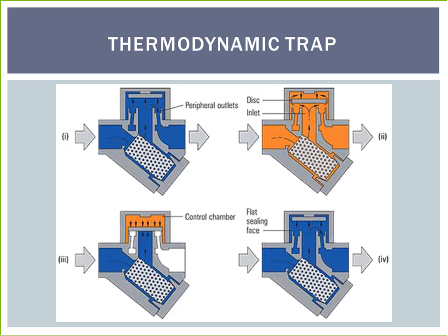At this point, the flash steam is trapped in the upper chamber, and the pressure above the disc equals the pressure being applied to the underside of the disc from the inner ring. However, the top of the disc is subject to a greater force than the underside, as it has a greater surface area. Eventually, the trapped pressure in the upper chamber falls as the flash steam condenses. The disc is raised by the now higher condensate pressure, and the cycle repeats as shown in Figure 4.